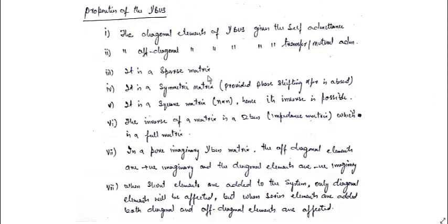The third property: it is a sparse matrix. We'll come to know shortly what this means. It means most of the elements of the Ybus are zero. Diagonal elements will always be there, but in a 10 bus system, for example, bus 5 will not be connected to all the other buses, and when any particular bus is not connected to another particular bus, the admittance between these two can be considered zero. Most buses will not be connected to most of the other buses, so you will see the elements of the matrix are mostly zero, and that is what is meant by a sparse matrix.